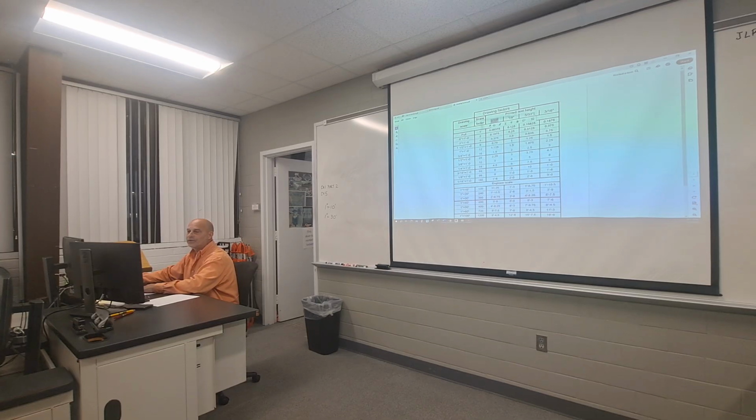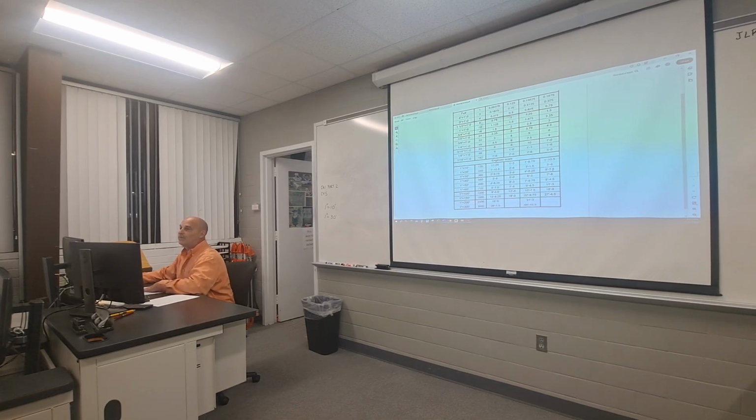3/32 for just general text, 5/32 for label text, like your north arrow. We'll talk about some more labels that you're going to have on the drawing. Down here at the bottom, you do have those two columns complete: your 3/32 text height and your 5/32 text height for all of these scales. You will not be using all of those scales, but since you don't know any better, now is the best time to go ahead and put them in.